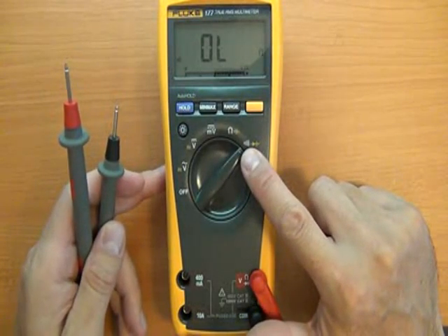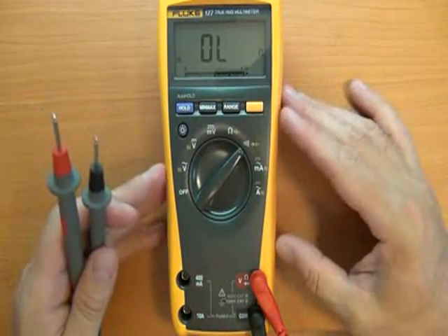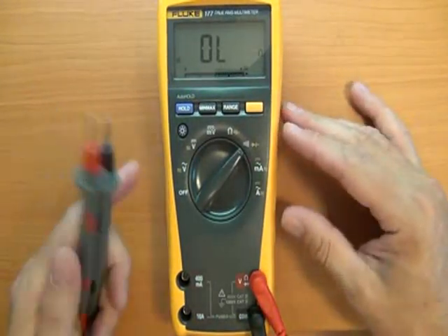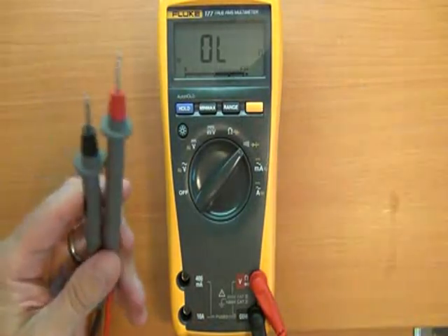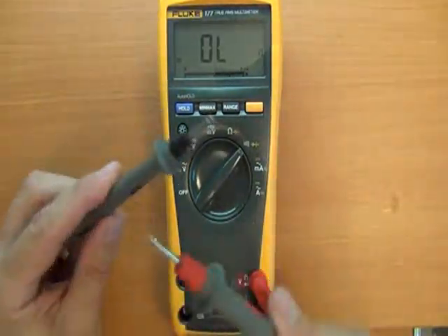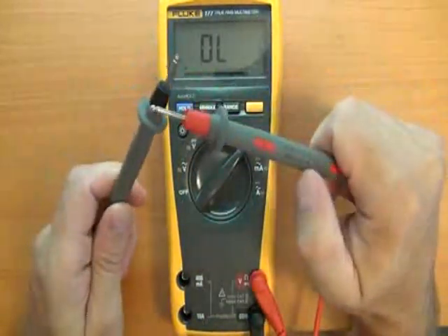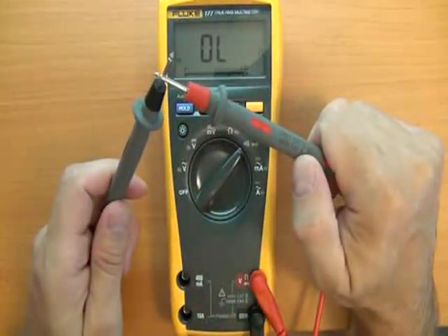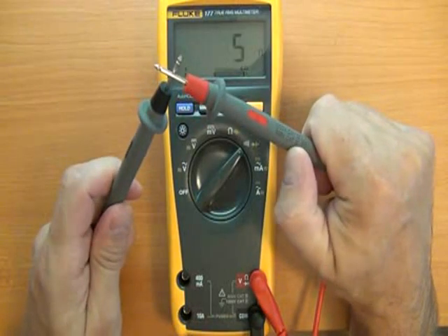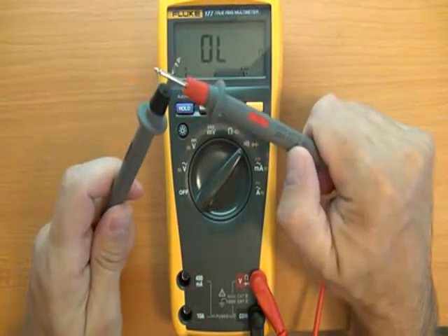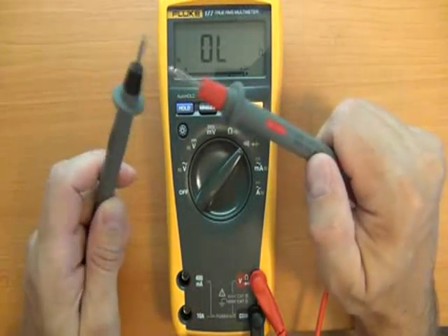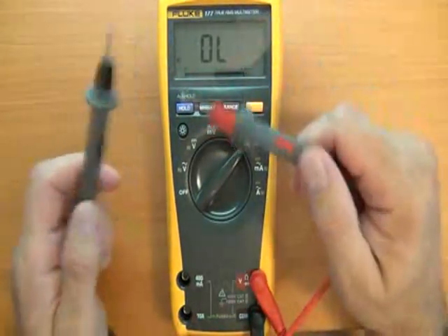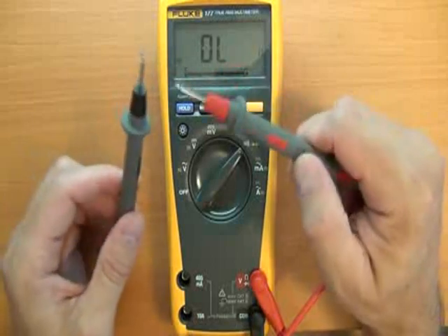Now I want to highlight the one handy feature on a Fluke, which, if you look at my multimeter reviews, is something the Flukes are renowned for. The one thing to do is always to check that your meter is working correctly. Hold your two leads together. Make sure you get a good response, so that you don't start testing, and if your battery or something's wrong with your leads or your meter, you suddenly don't get the results you want.